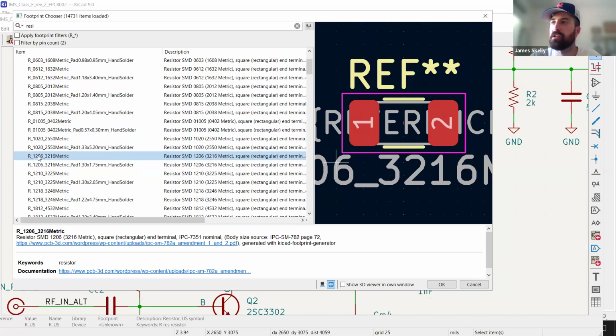Yeah, so multiple things are happening at once. Typically you will build the schematic first and you'll test to make sure that the circuit is actually going to work. And that's purely schematic and simulation based. That's not even considering real parts yet. Then you say, okay, I've built the circuit, I'm happy with it. I'm going to check my simulation to see how much power this particular resistor needs to be able to withstand.